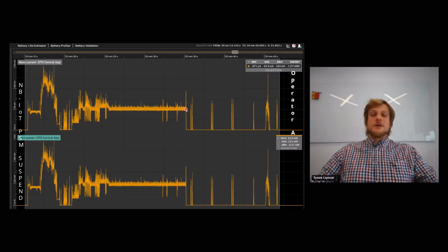After 10 seconds of no data activity, the network releases the RRC connection, the modem goes into active time, does paging, paging, anything for me, hello. Then we have preparation for suspend, last blip, and then we are down to below 4 microamps of current consumption.